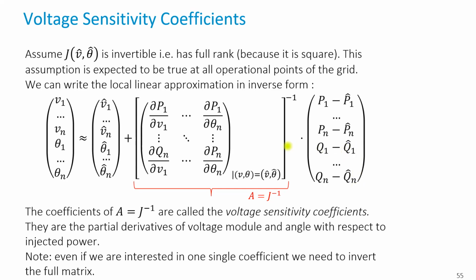Well, at solar panel inverters, for example, I can change the cos phi, the angle of the power injected by the inverters. That will typically be at a small cost of reducing slightly the active power that's generated, but only very minimally. And that will be taken care of by the other term of the objective function we had, that will be compensated by the slack bus.